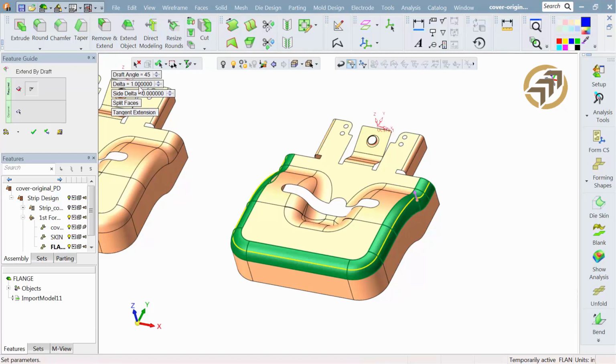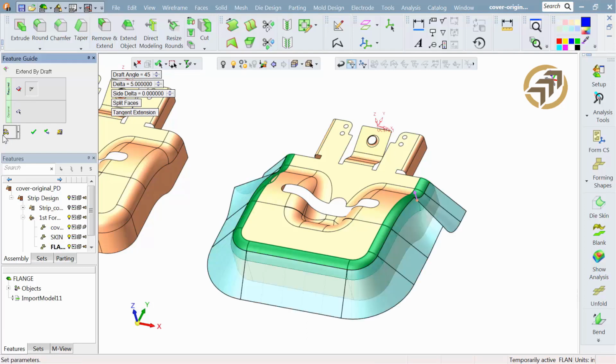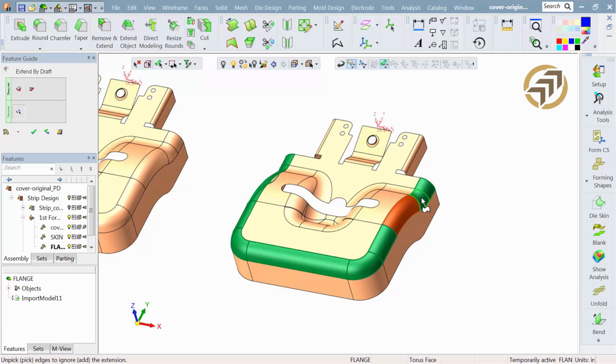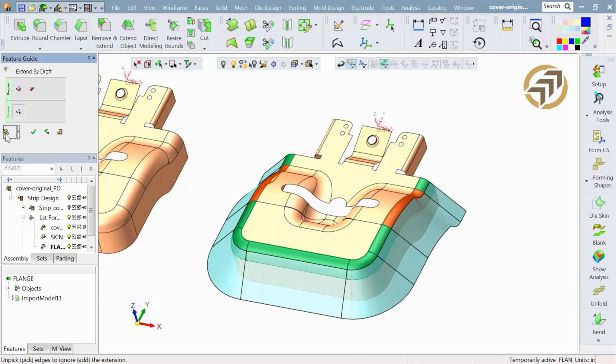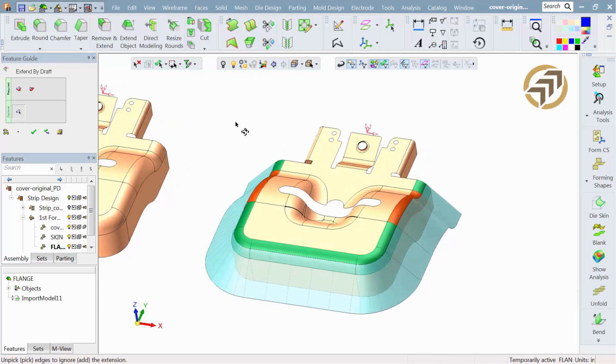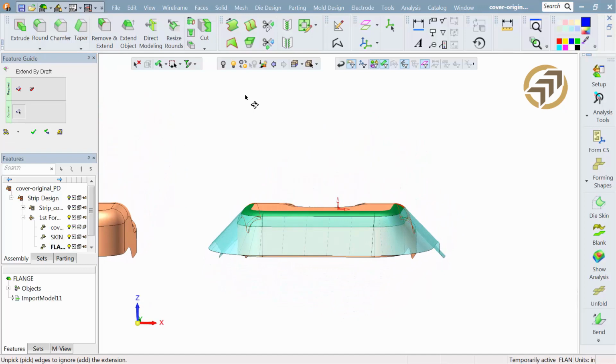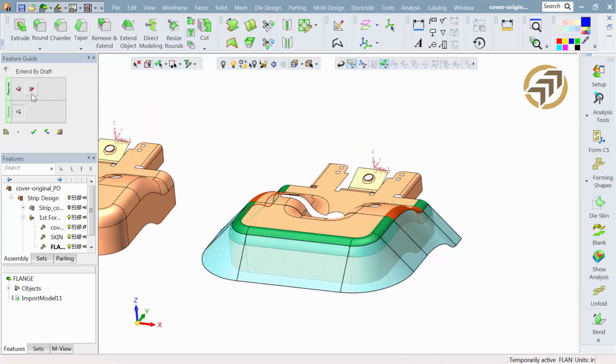So we're going to create what's called a binder, or a face that's going to come off at an angle, here at 45 degrees. If you're not happy with some of the surface conditions I see, you have a nice smoothing tool, or a patch tool we like to call it, that interrogates the part and says, well, we can do a little better job here. Let's smooth across those areas to get that binder that we want.